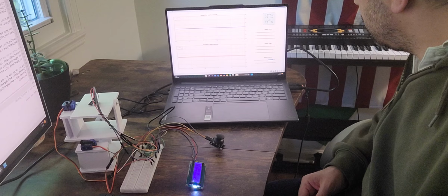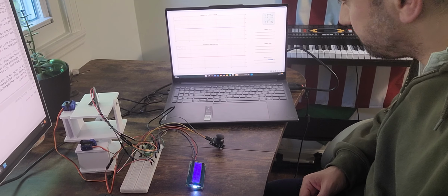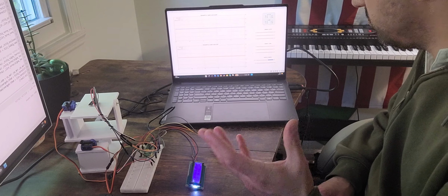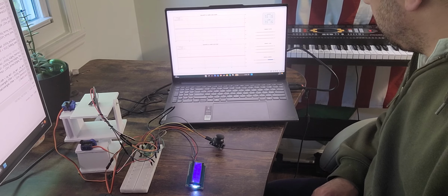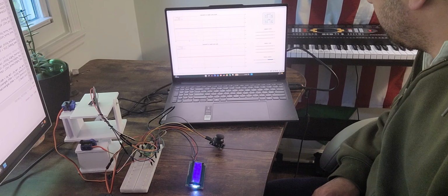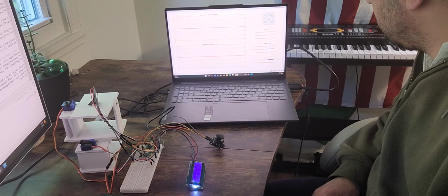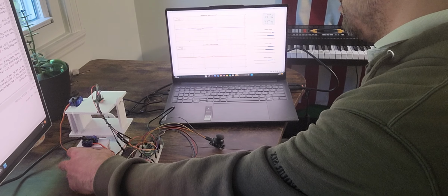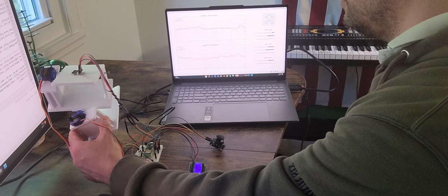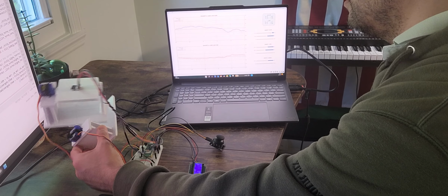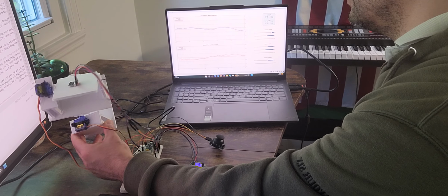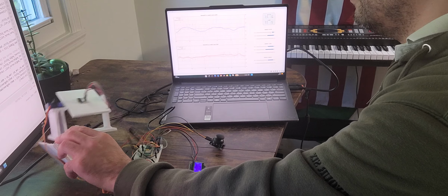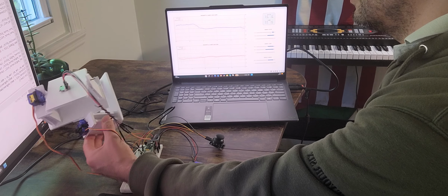So I'll put it to the predefined optimum value of about 0.52, and then I can set my gains at relatively optimum values. Now if I do this, it's more stable, it doesn't vibrate as much, but it's a little bit sluggish because of that. So there's a bit of a trade-off there, right? It still does what it is supposed to do, you see.